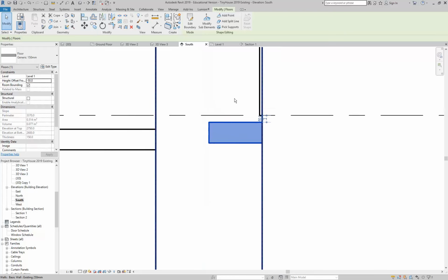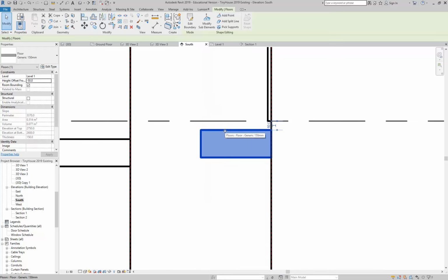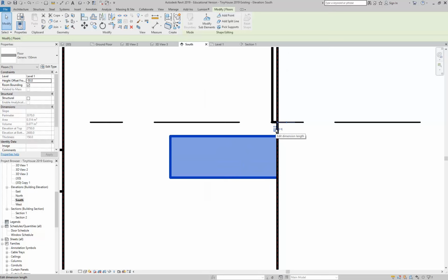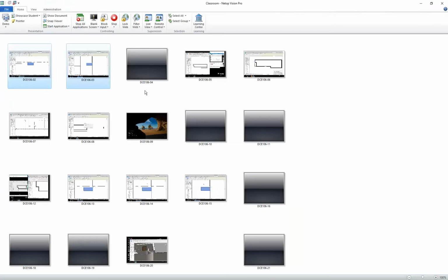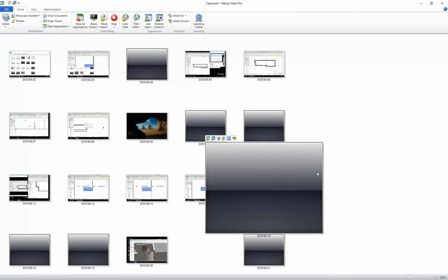That's not good. These days, that's another thing that wouldn't comply with the BCA, because they don't want small thresholds. There are all sorts of workarounds and New South Wales exceptions to that rule if you go right through the BCA. But there's a good reason for it: it's so you don't trip over when you've got little steps. So have a think about that. But again, maybe I'll just do it 50 just for the sake of it, so you've got at least some sort of threshold. And I'm just going to release you guys over there, because I think I took you over.